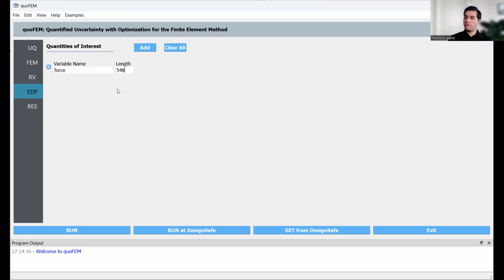And with that, we have everything ready for the parametric study, right? Notice that we haven't provided the program any information from the experimental test, and that's because we are not interested in simulating that. We're not yet quantifying any error with the experimental test. The only thing we're doing is running the analysis for a range of lower and upper bounds of our parameters.